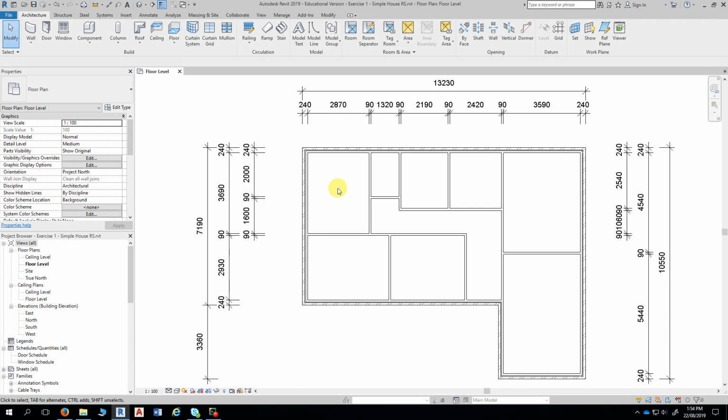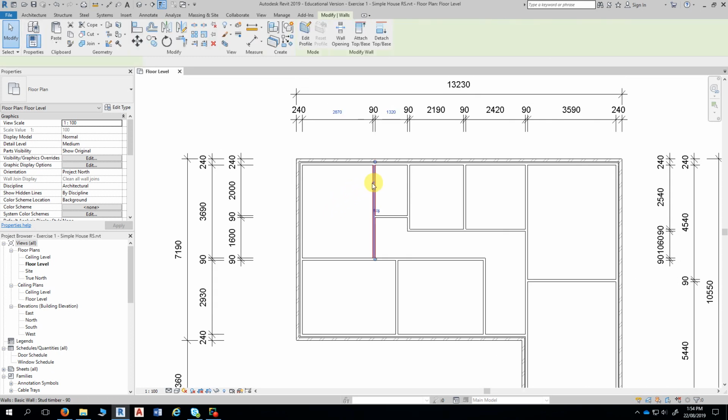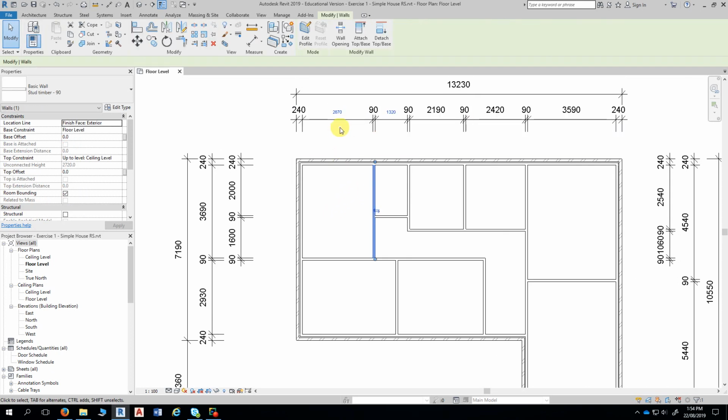So to move the wall, we have to select it, so it becomes an edit function. In selecting the wall, the dimension activates. See how this one is now active and this one is active. So I can now click directly on the dimension. But you can't click on the dimension first. You've got to select the wall first, which activates the dimension, then click the dimension and update it. Okay, so 3200. It moves the wall to the right in this case.